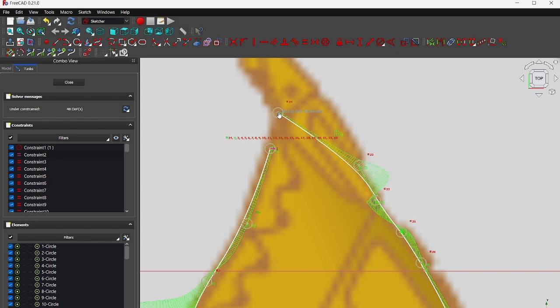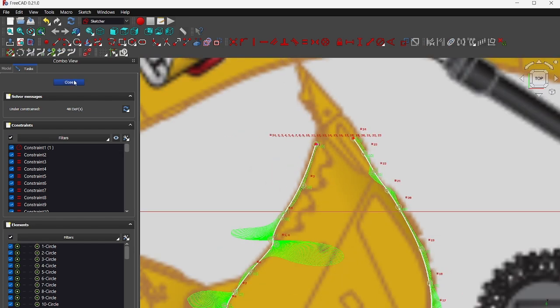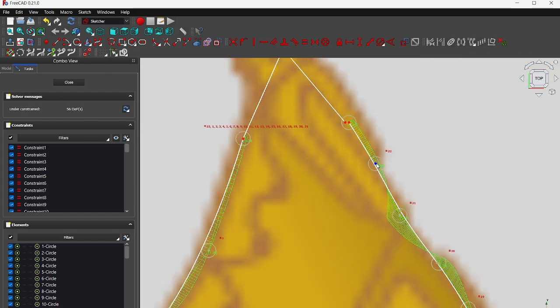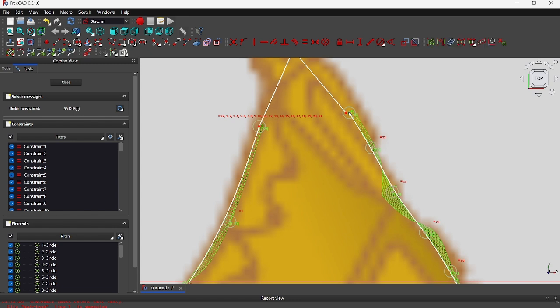Let's say here is the endpoint for the B-spline, switch to polyline, and define the smooth point. Remove redundant constraints and adjust this point to be as smooth as is best. Also, you can adjust the B-spline and connect points. In this FreeCAD version, which is 0.21,